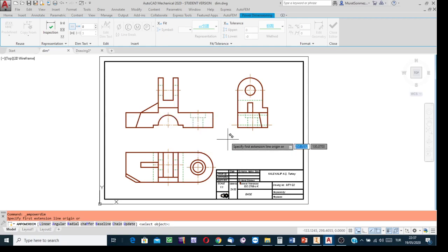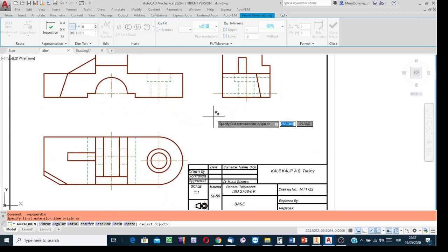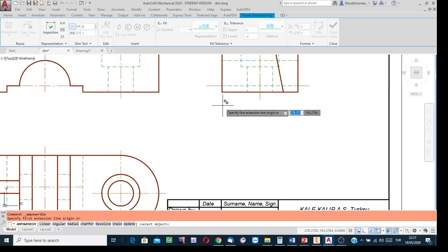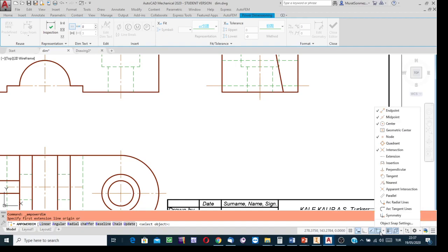For instance, show the depth of the object. I selected as the suitable projection plane the left side primary profile picture plane, and on this view I'm going to show it. Of course, to be able to indicate the terminal points of the features, use the snap facility. I already toggled on the snap enabling button, and then I need to indicate the endpoints.